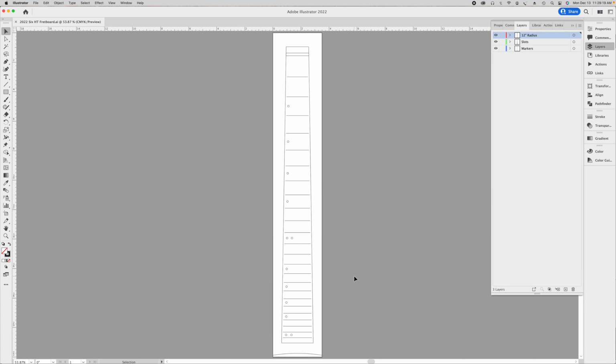So this also is going to play a pivotal role later on in future videos when I talk about how I do two-sided carving. So it's just a good practice to make sure that whenever you create these drawings, they're centered within the document size, and the document size should be exactly what your blank size is. Once I have finished my top-down, full-size, full-scale, two-dimensional drawing, I can save out the elements in the appropriate file formats and begin the process of developing my CAM strategy.